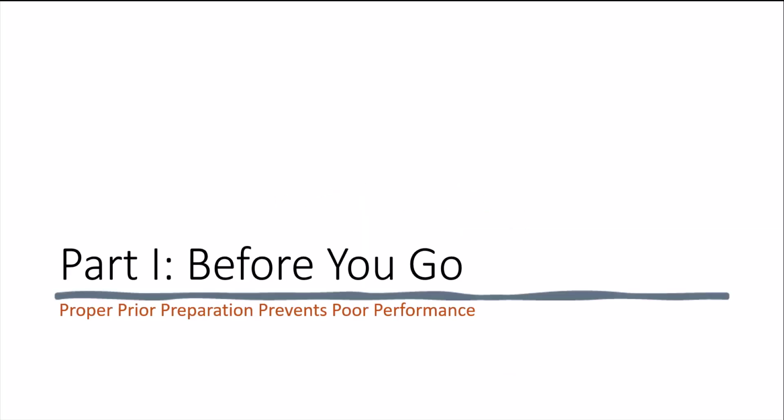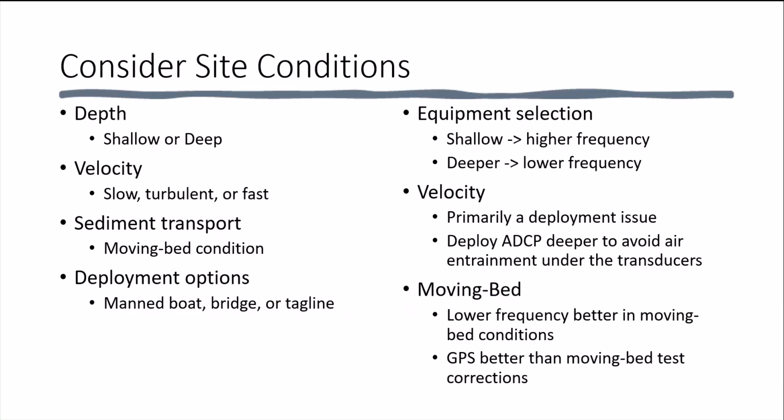Preparation in the office is key to successful data collection in the field. First, consider the site conditions. The depth, is it shallow or deep? The velocity, is it slow, turbulent, or fast? The sediment transport, is there potential for a moving bed condition? What are your deployment options, a manned boat or a tethered boat from a bridge or tagline? These are important when making equipment selection.